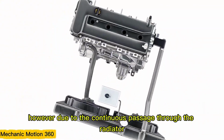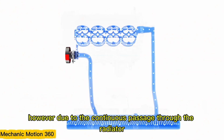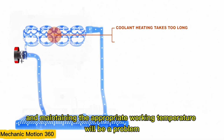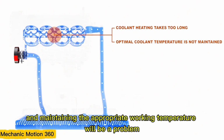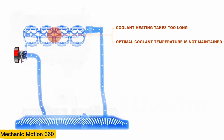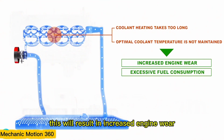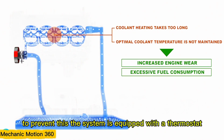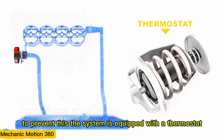However, due to the continuous passage through the radiator, it will take a long time to heat the coolant in this instance, and maintaining the appropriate working temperature will be a problem. This will result in increased engine wear and excessive fuel consumption. To prevent this, the system is equipped with a thermostat.